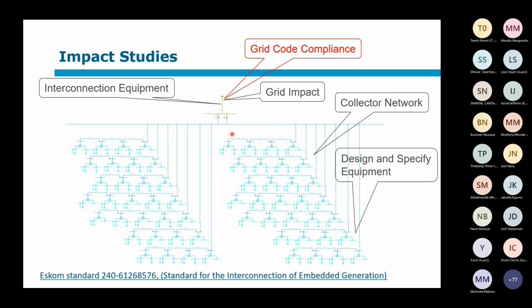Now, this is something that I think is a little bit of a concern, because I know Eskom has got reasonable network models with which one can do this. Some of the municipalities have got their networks up to medium voltage. Resonances are typically less of a concern there or easier to determine because it's short lines in the medium voltage network. But that is something that remains the responsibility of the distributor. And then, of course, the protection coordination.